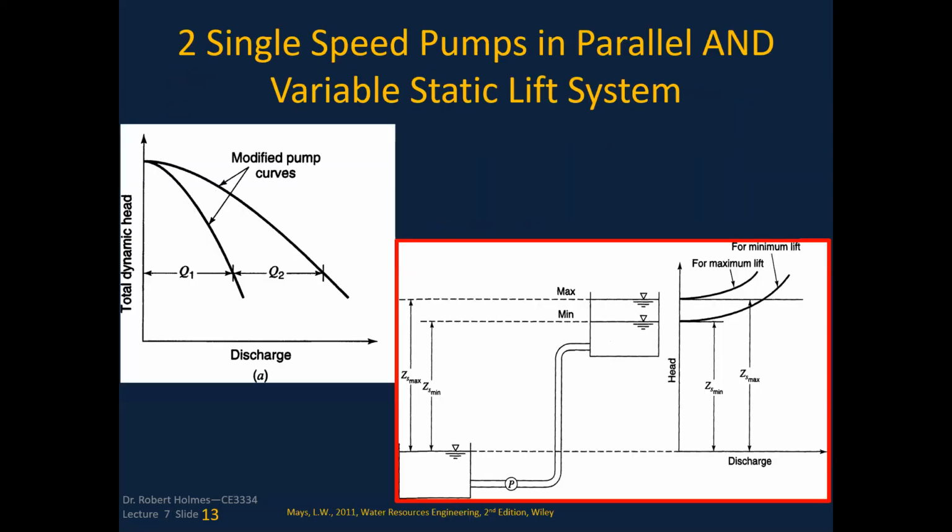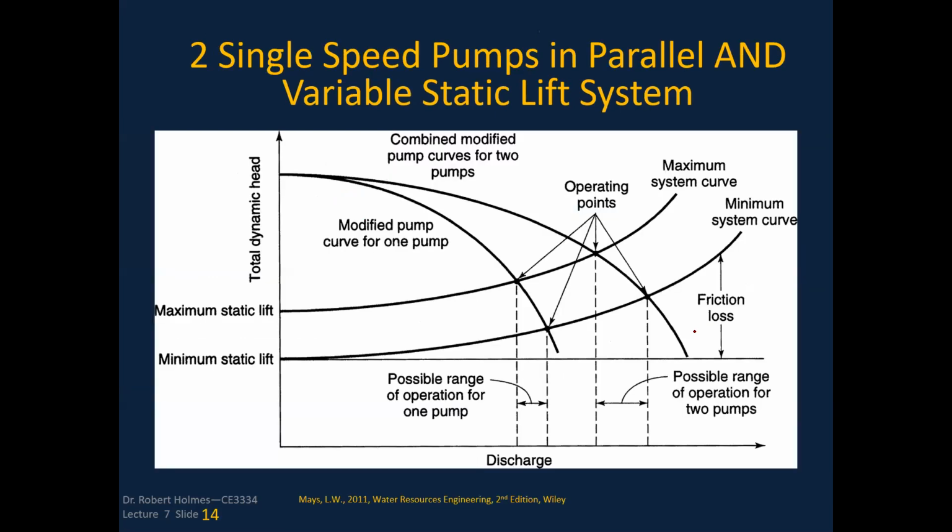So let's look at some more different kinds of things here. Again, if I threw this up to you, this was two different pumps, what would this tell you? This is two pumps operating in parallel or in series. Because we're adding no more head, I'm going to say these are acting in parallel because it's adding discharge but not additional head. We've already talked about this maximum lift stuff that was on a previous slide.